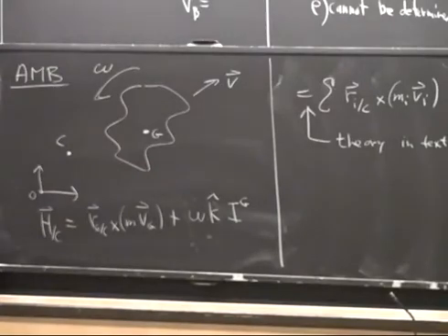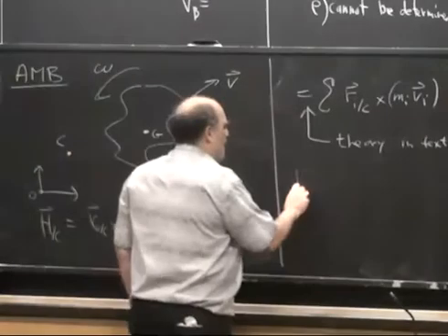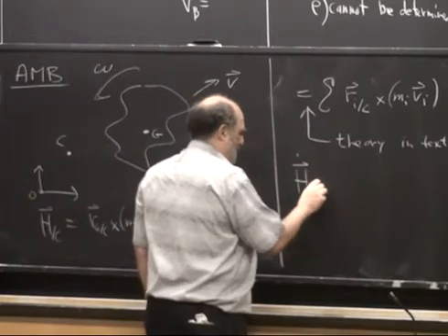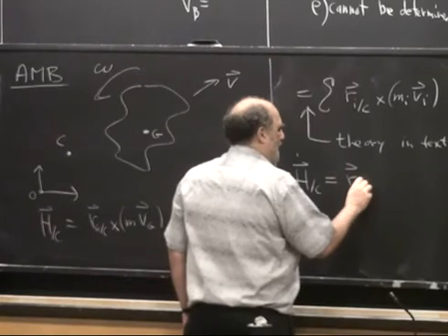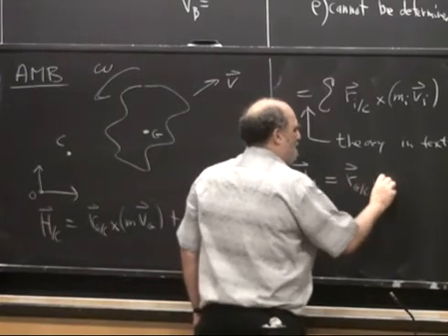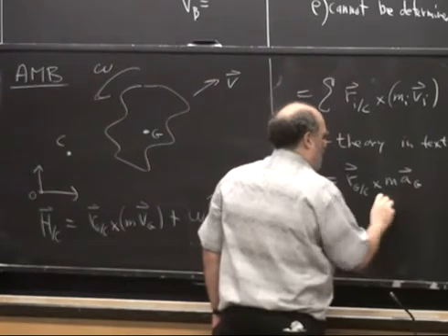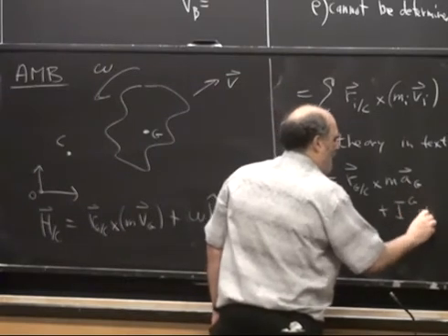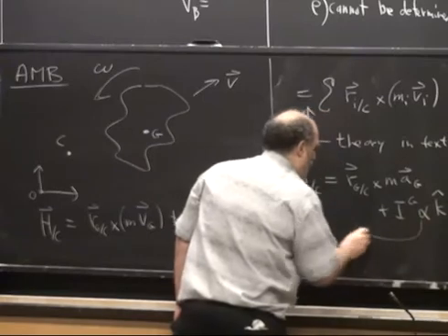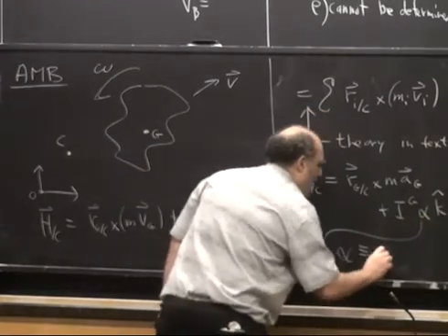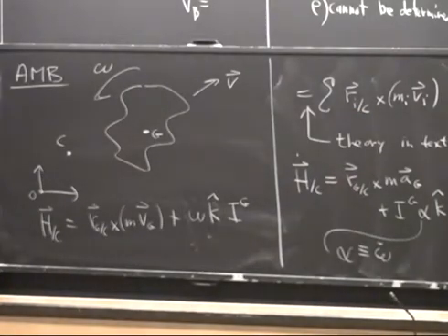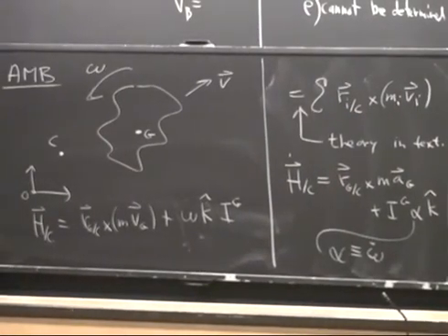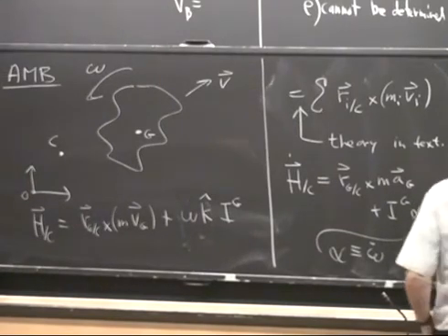So once you've done that algebra, we can also get that the time derivative of this quantity, which is the thing we need for mechanics, is equal to the position of G with respect to C crossed with the mass times the acceleration of G plus Ig alpha k. And this thing alpha we'll define to be omega dot. And from this we can do mechanics problems. So the most famous of these mechanics problems is the pendulum. So let's work out the pendulum.